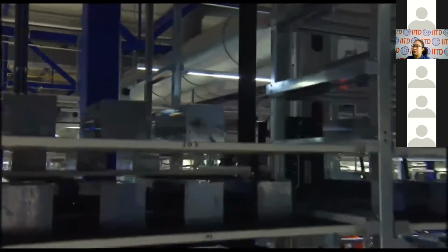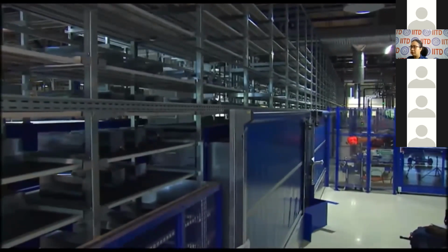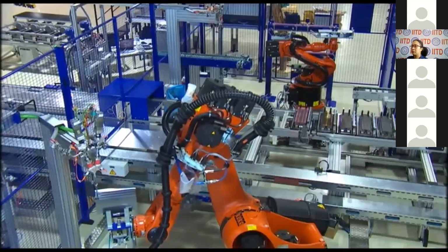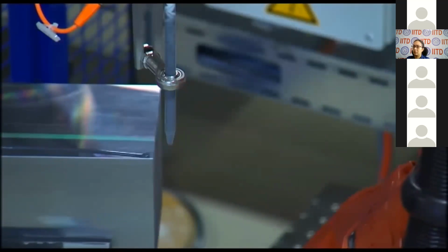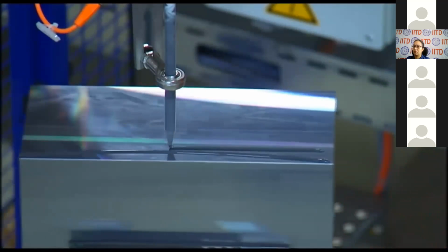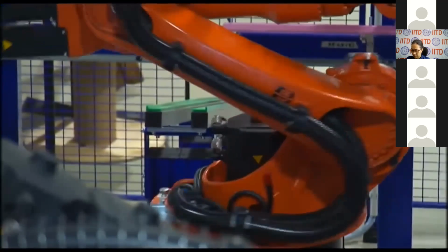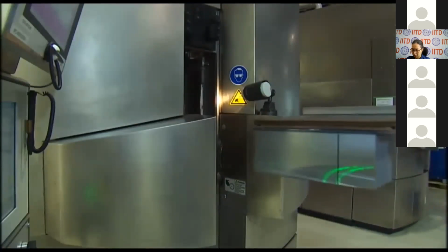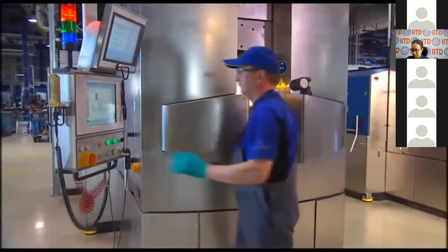Via the fully automatic shelving system, the pre-sorted silicon bricks are then transferred to the wafer fabrication stage. The bricks are bonded to both a glass plate and a carrier panel, a technology that has been developed and continually improved by SolarWorld's experts. In the wire saw section, which comes right after the bonding center, another wire saw process is used to cut the bricks into thin discs, the so-called wafers.